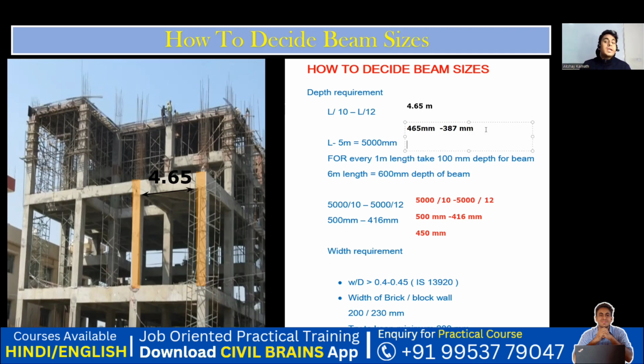Again, you can take 450, but instead of taking 450, you can take the average of that. So we'll go with 425. 425 is a very decent size I can have. So I'll go with 425 mm as the depth of the beam. Again, it is not a final size, but a tentative one. Maybe the final will come out somewhere close to this, or there's every chance this may be our final. It depends unless we try to design that. How the designing has to be done, I'll be taking up in the upcoming lectures.